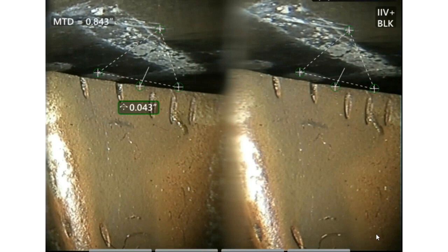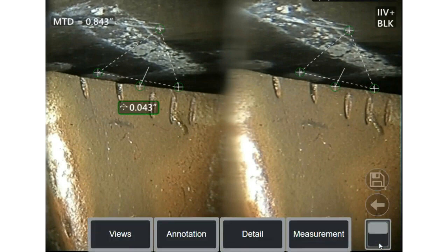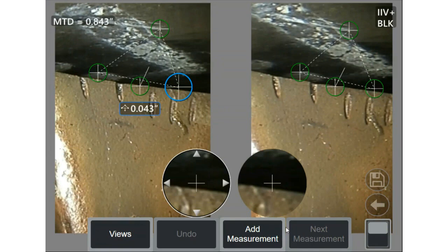So what's happened in this measurement, if I double click in this lower area, you'll see there's a toggle area that I can completely mask out and hide, and I can activate the measurement data. And what my task is as an inspector measuring with stereo is to look at cursor 1 on my side and the placement of cursor 1 on the computer side, and those have to be on exactly the same pixel, and if not, you will not get an accurate measurement.